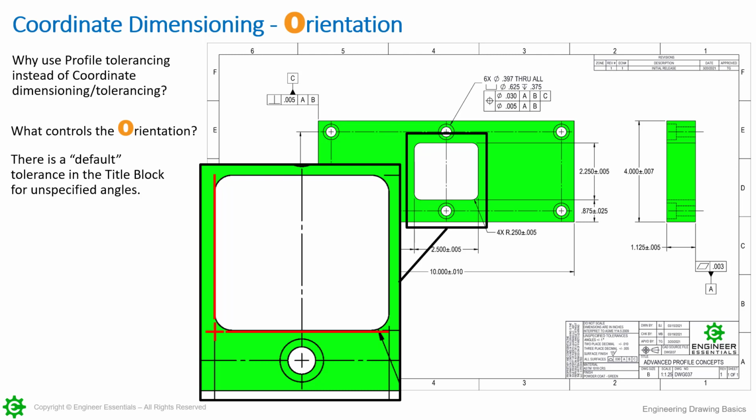Now you might wonder, why am I not starting at the top of the radius? So look at where I've thrown the tolerance zone down here. It's down there at that surface that's located 7/8 from the datum feature. Again, not the datum. The reason that I've done this, and if you go into Y14.5, there's a conflict here.